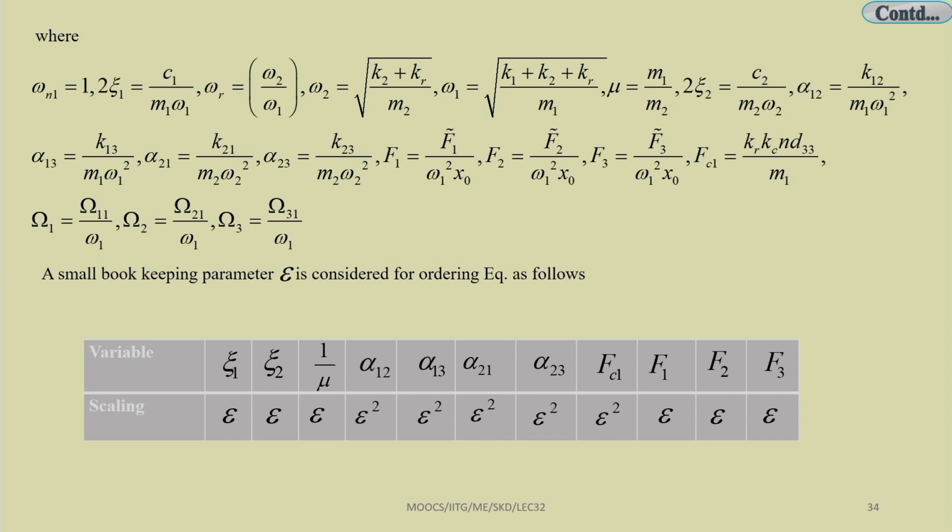You may also use the weighted modal matrix. So, instead of the modal matrix P, one can use the weighted modal matrix. In that case the resulting mass matrix will be the unit matrix, so I will be equal to the identity matrix, and the coefficient of x, that is the displacement, will contain the eigenvalues of the system. So, it may be omega 1 square, 0, 0, omega 2 square. That way also one can write another set of equations.